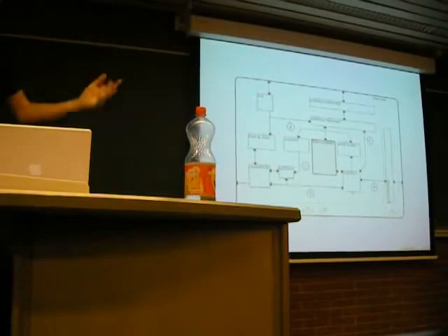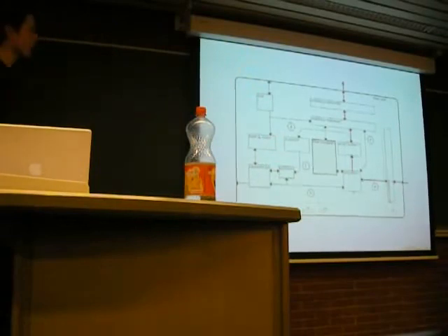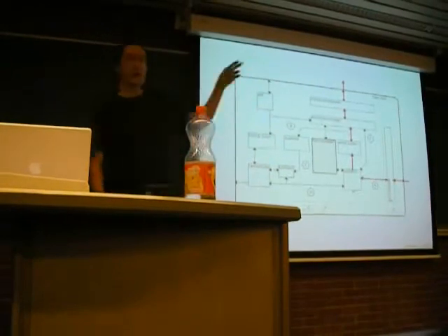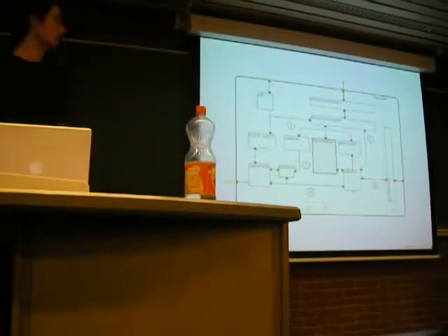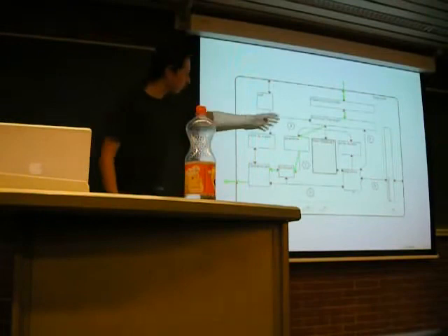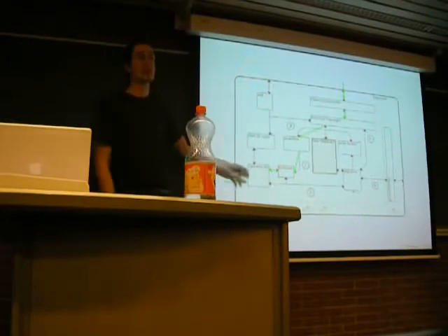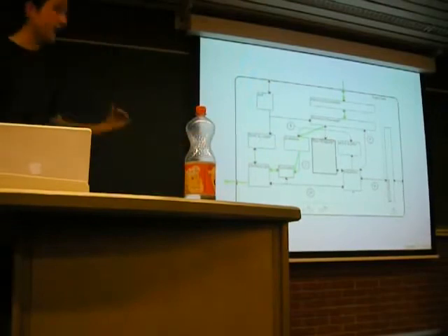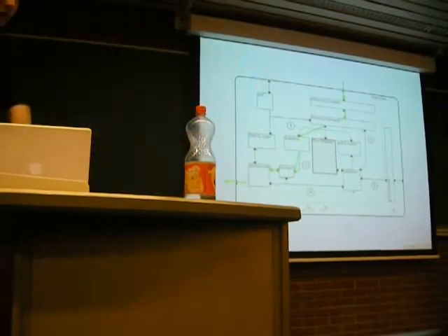So if we compare this with Project VGA, the data comes in through the PCI controller and is sent out to memory. Then if it needs to be drawn, it comes back from the memory and goes out through the raster scanner, and the raster scanner does the translation just in time. And then it goes out. So it's really a lot easier to implement.